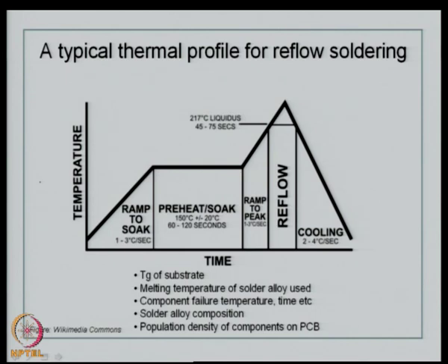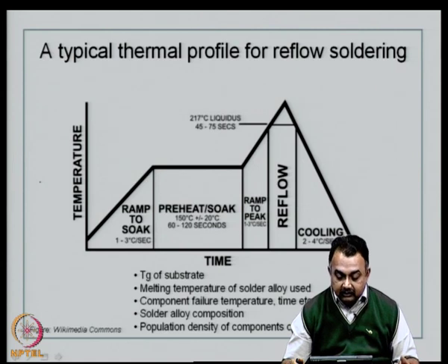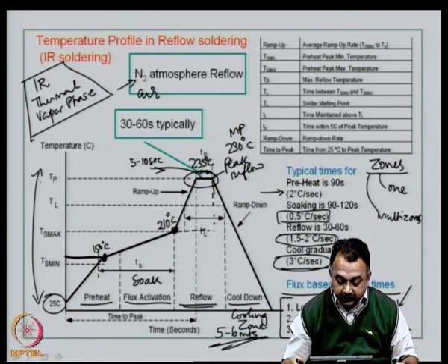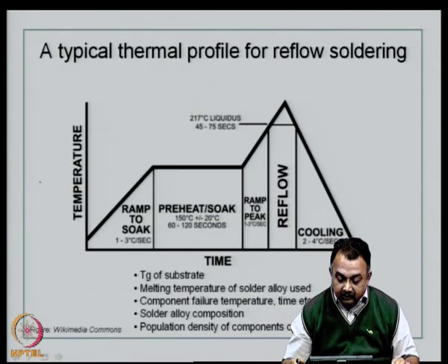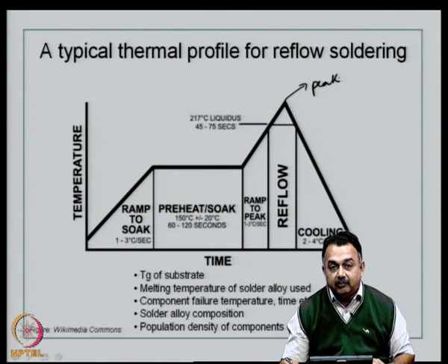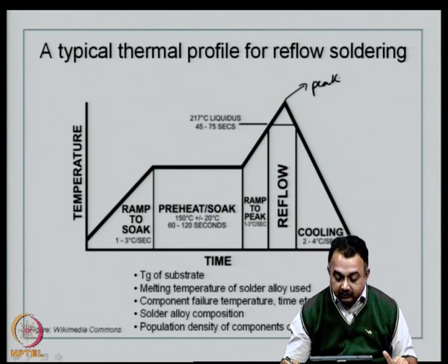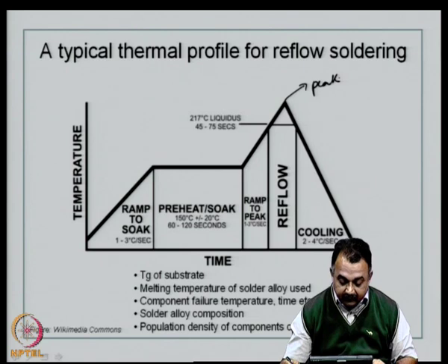Now, this is another thermal profile for reflow soldering. The earlier one, you can see the shape of the thermal profile is quite different, right. Now, here you can see that there is no residence time, there is a peak here. There is no residence time that the board spends at the peak reflow zone. So, that depends again on your judgment of all the various parameters.